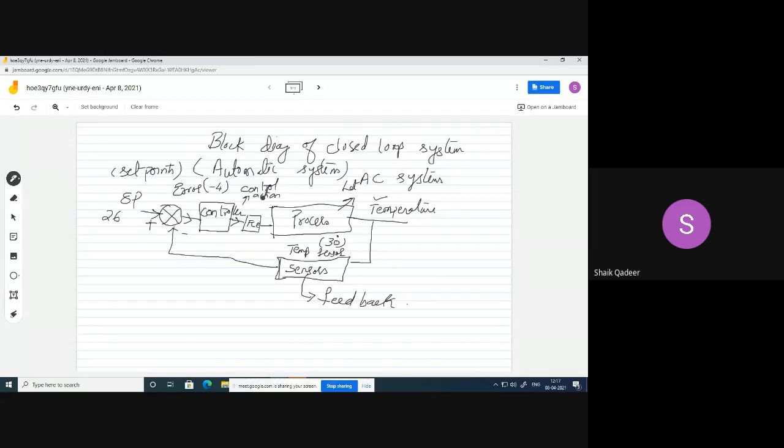That control action does not have direct influence on the process. Instead, it influences another element called the FCE, the final control element. In the present case, this final control element is the excitation to the compressor. Agree or not?